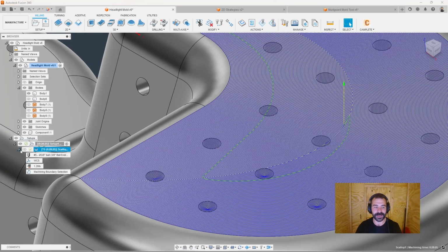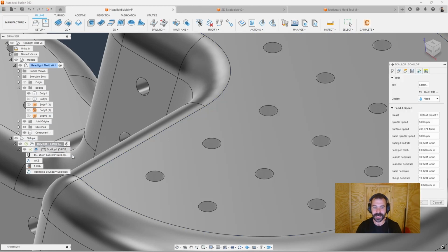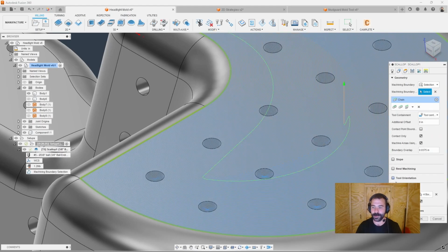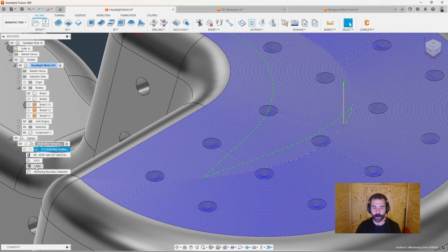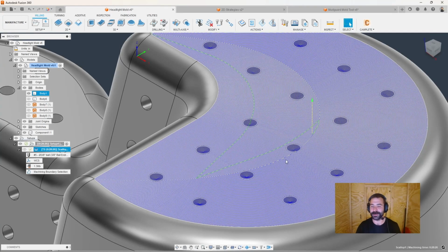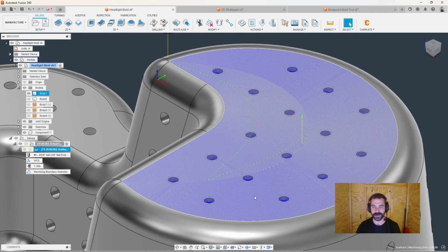One big thing to look at too, for you guys out there, is if we start looking at the file size that we're working with, you'll see that taking effect by a reduction of points. So again, we're at 1.2. We turn off model. We hit OK. This should go up to 1.9. Actually, 1.3. It came back down. So we are creating more points, which means more data in our toolpath.